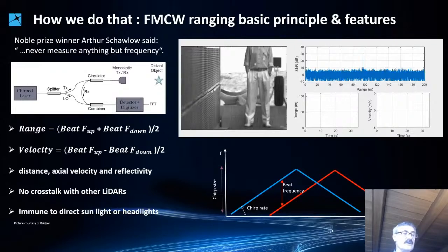The inset shows the schematics of the FMCW LiDAR. Frequency modulated optical signal of the local oscillator, usually with linear modulated waveform, is sent to detector and to the sensing scene. The return signal, which contains information about location, speed, reflectivity, etc. of the sensed object, is mixed at detector with the local oscillator signal.